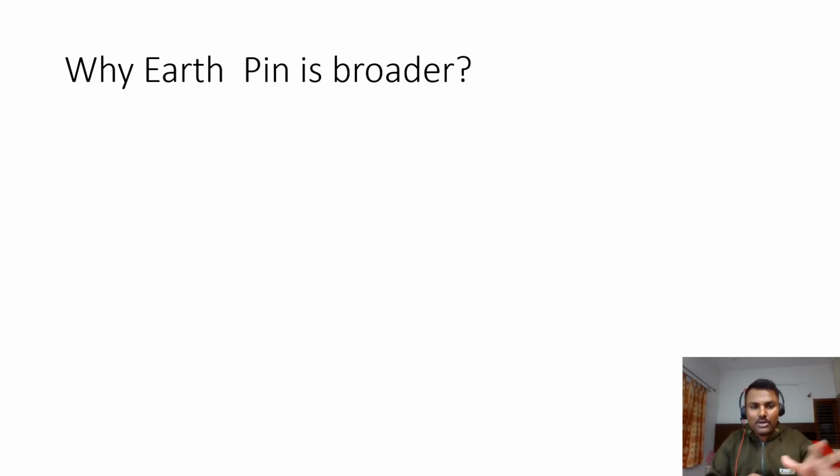you touch the body of the product, if that body is metal, and inside the product any positive line is connected to the body by mistake, or wrongly connected, or by dropping the product somehow the current is leaked and the wire is connected to the product body, then if you touch that metal body, current flows through your body and you will feel an electric shock.